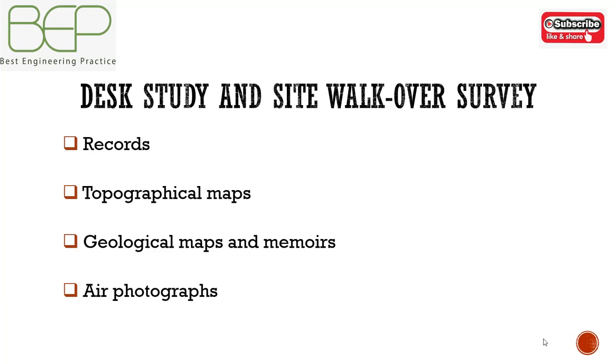Desk studies are important because the type of retaining structure to be used will often depend on soil conditions. They are also important because the type of work to be carried out during site investigations will depend on the soil conditions encountered.